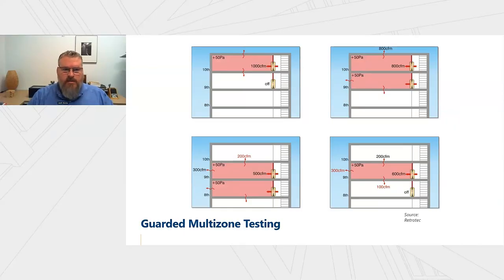The standards do allow for this. And you usually have to test a certain percentage of the floors, but you definitely have to test the first floor and the top floor and the ground floor, because that's where the bottom piece of your air barrier is, and the lid of your air barrier is at the top. But you do that with a series of tests.